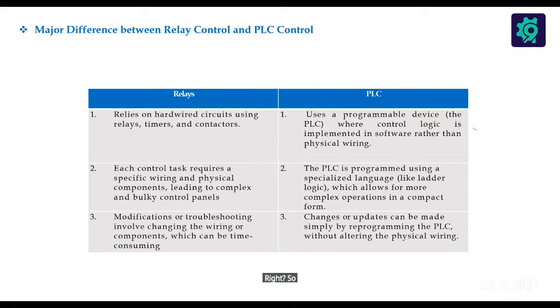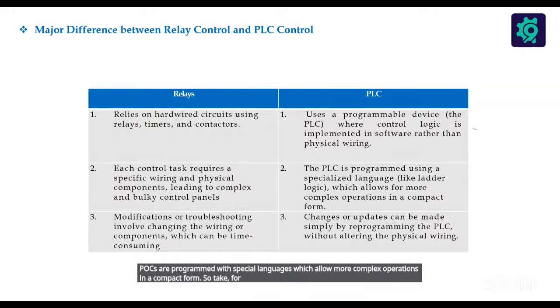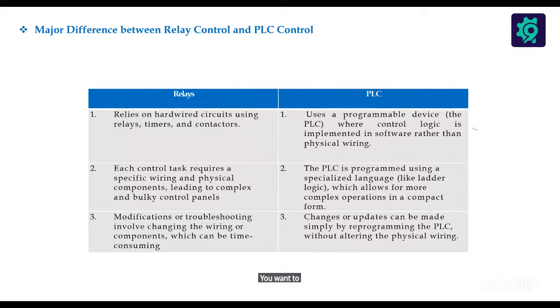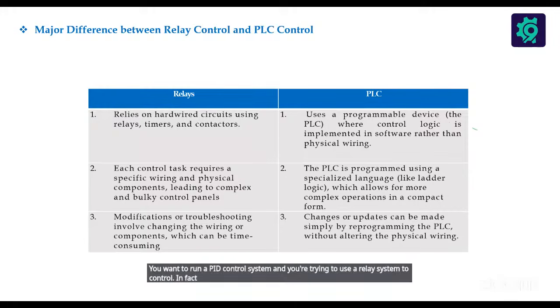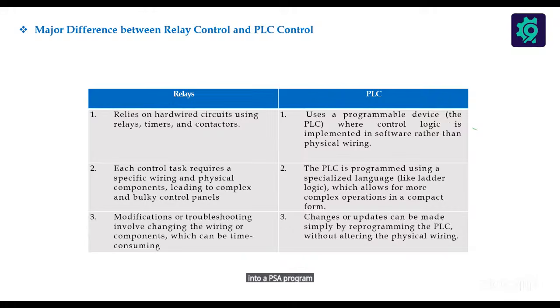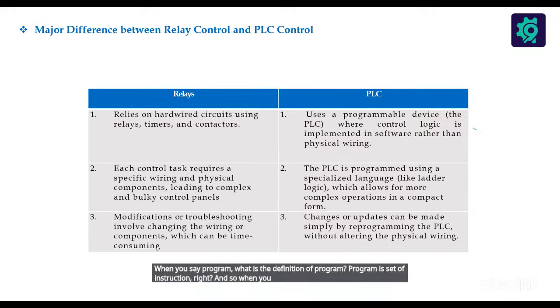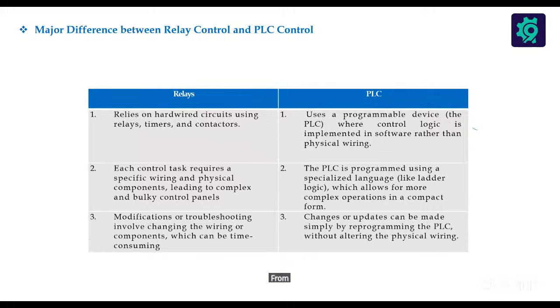Another thing is that PLCs are programmed with special languages which allow more complex operations in a compact form. So, take for instance, you want to run a PID control system and you're trying to use a relay system to control it. Even thinking about it alone is complex to the mind already, right? It's complex, but you can easily fit this into a PLC program. When you say program, what is the definition of program? A program is a set of instructions, right? And from your formula for PID alone, you can use that mathematical formula to build an algorithm and design it into your PLC program.